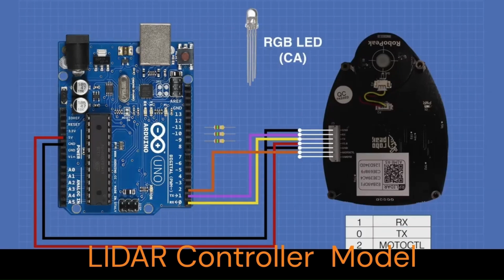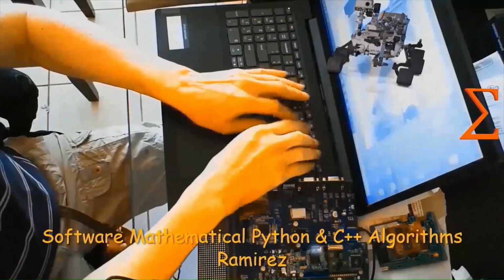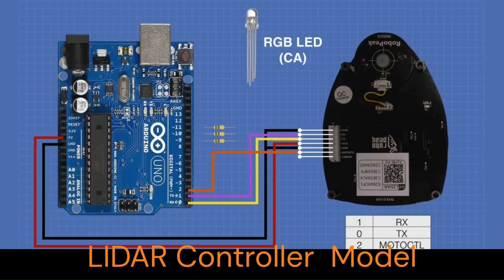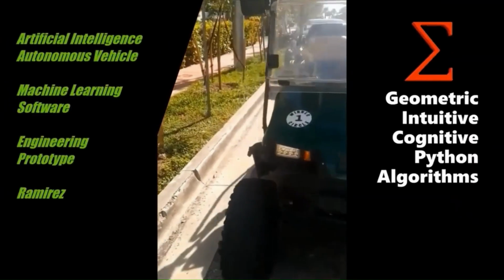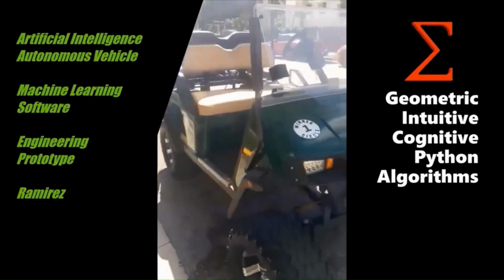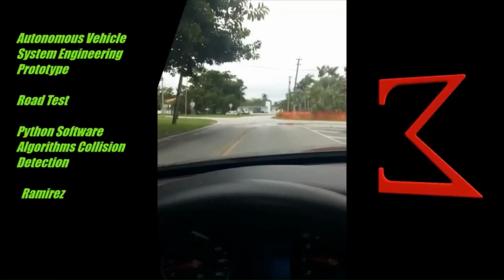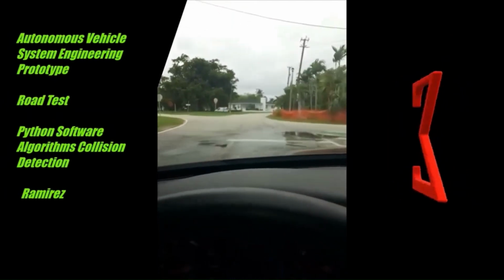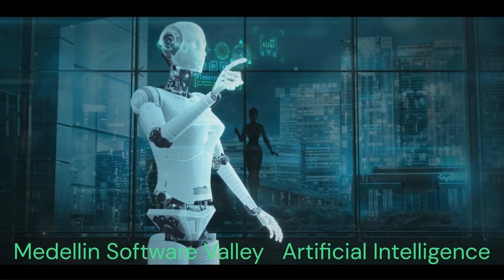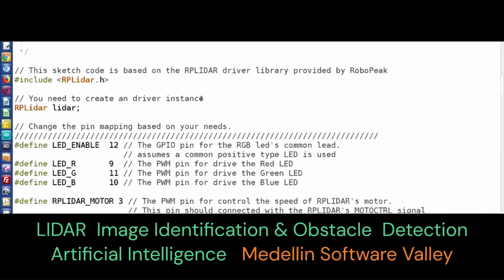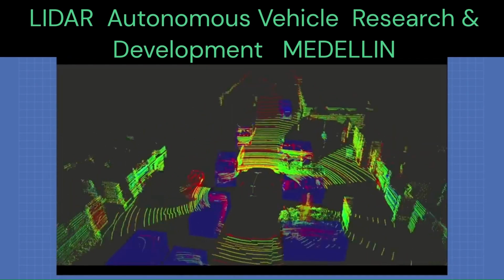Now, we can apply continuous wave LIDAR, which is different than the pulse LIDAR. It uses either amplitude modulation or frequency modulation of the light source. In amplitude modulated continuous wave LIDAR, the system typically operates at a wavelength of 905, 1300, or 1550 nanometers.